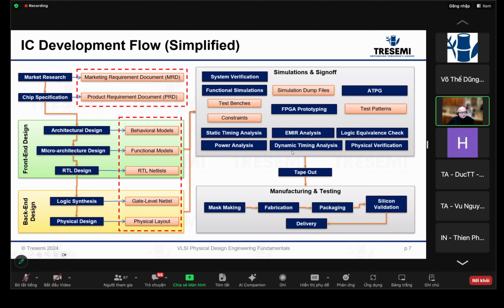So there are certain test patterns that need to be run in the dynamic mode. And also, of course, physical verification is the verification of the final physical view against the transistor level netlist, because mathematically the transistor level netlist can be compared with the behavior model via different methodology, but the physical layout somehow has to be mapped into the transistors.